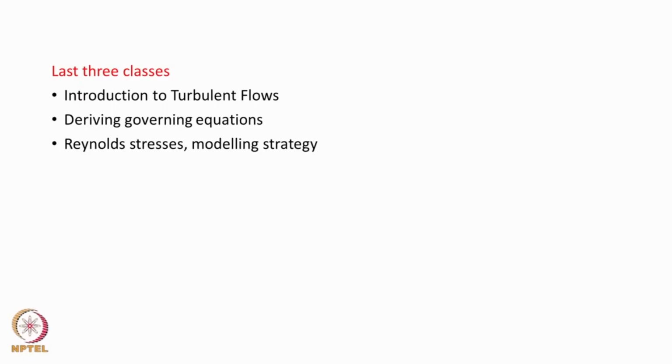Greetings and welcome again to this course on CFD. In the last 3 classes, what we had seen: introduction to turbulent flows, we tried to derive the governing equation for turbulent flows, and tried to understand the term Reynolds stresses. Reynolds stresses have 2 main components, one is a normal stress, the other one is a shear stress. Totally there are 6 unknown stresses.